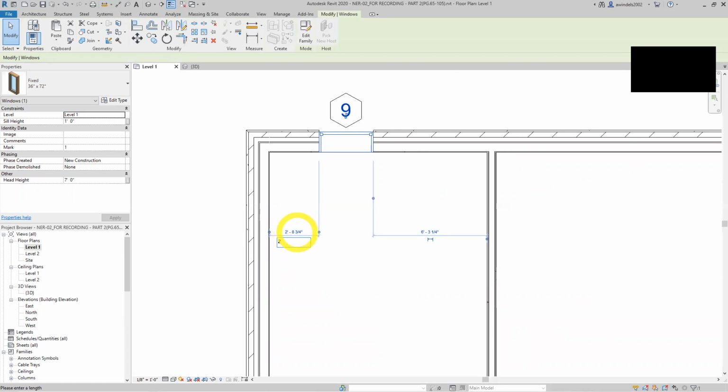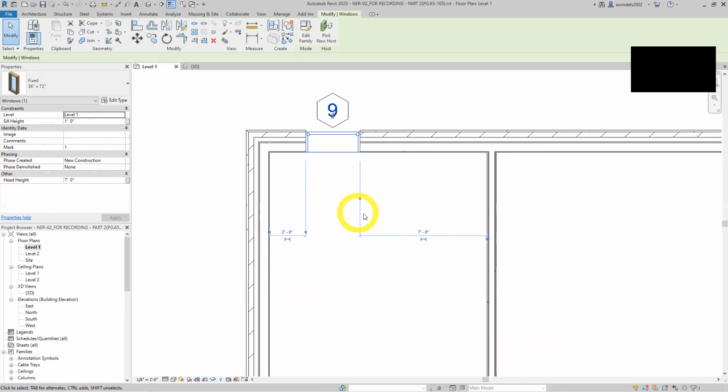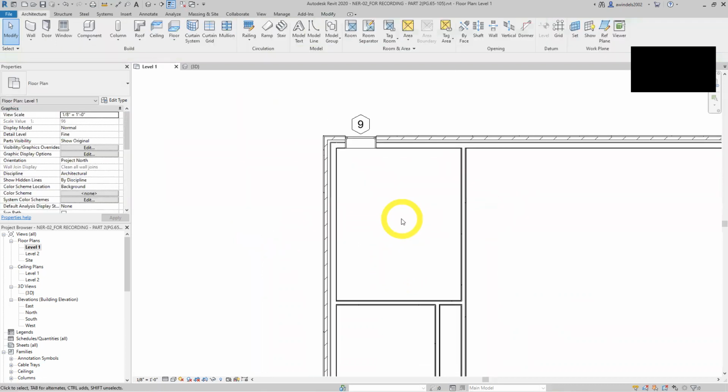I would have shown you this earlier, but one little new editing tool at a time. 2 feet. It's saying in this case, we want to go from here 2 feet. So let's just go there. Drag it. Now we'll call it 2 feet. That's the power of those temporary dimensions. You can also move them to the exact datum before you change them, which can be helpful.